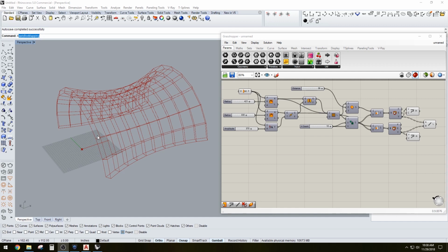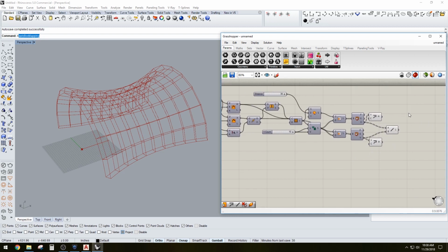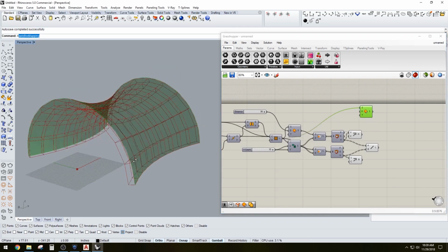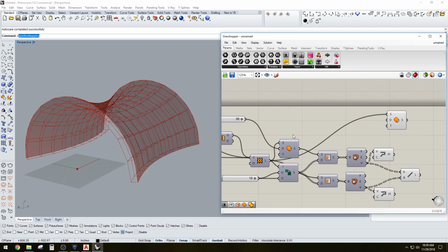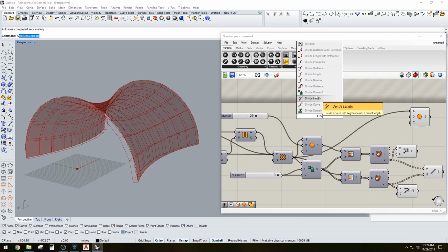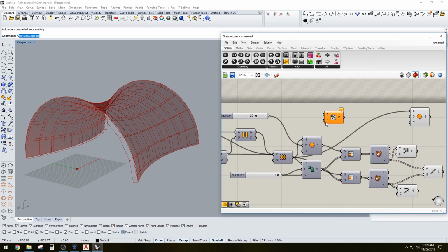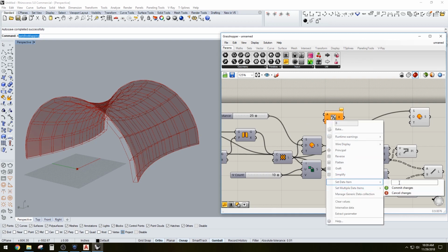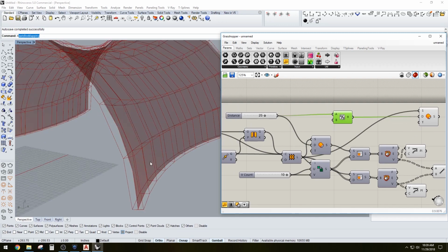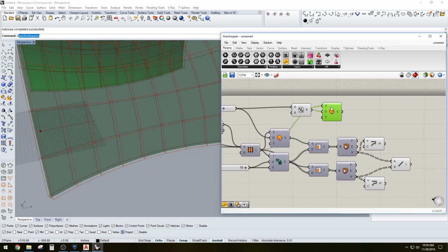So to create that point in the middle that we're going to connect to, there's going to be a few steps, but they're pretty straightforward and shouldn't be too tricky. So let's get on those. Let's offset that same loft. So we're creating that same surface, but we're doing it half of this distance, which is 36 we have right now. So let's divide, and then we'll add a 2 here. That way we don't have to create a slider, and then we'll go that distance halfway. So we've created that half distance there, and we'll isotrim.